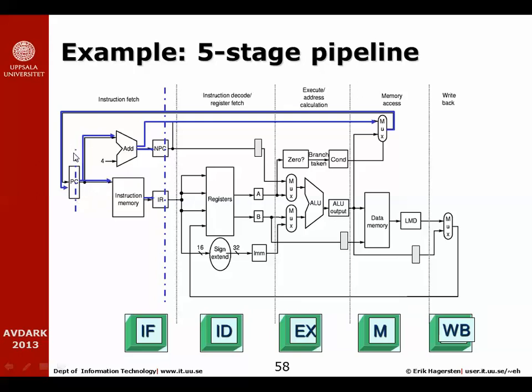And as you can also see, there is a latch here, so we're going to remember the new value at the end of that first instruction. So now we have the 32 bits representing the instruction sitting in this latch over here. In the very next cycle, those bits can be read out, and part of this representation of the instruction are bits representing which register to read and which register to write. So here we have the destination register, the source register, and the source register, so 3 register values that we will use to access the register file here to get the right selected registers out of this file.